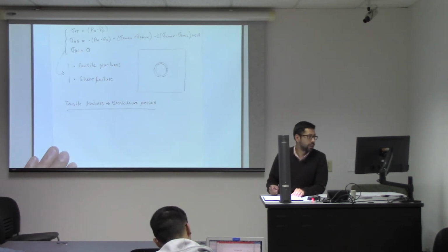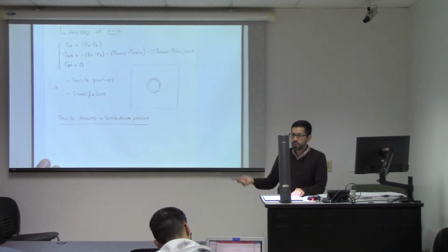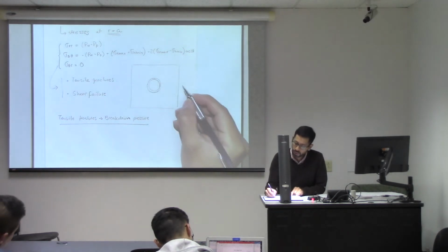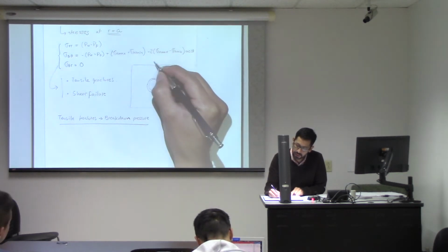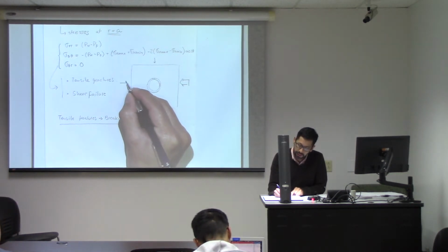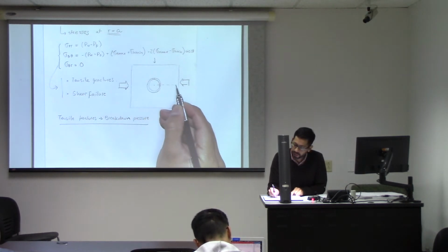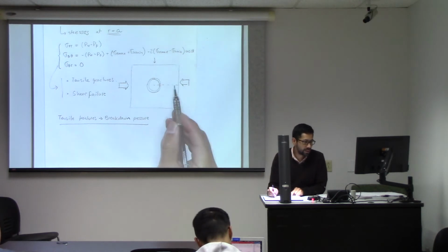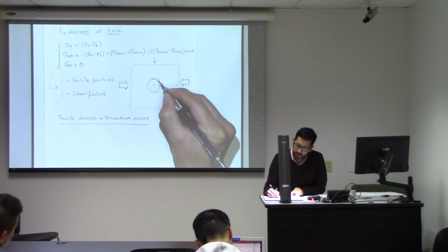Basically, what we want to do here is to calculate the minimum hoop stress around the wellbore so that I compare that to the tensile strength of the rock, and I check whether the rock is at failure or not. So if I had, say, for example, the maximum principal stress coming in this direction and the minimum in that direction, the angle theta, remember, is always going to be the angle between this stress and a particular element that I'm considering.